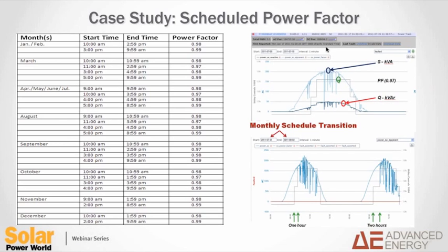And what this really enables the utility to do is, instead of having to invest in a large amount of SCADA and DMS infrastructure, they can conduct some studies offline and really position the inverter such that it's providing the right service at the right time in this fashion.